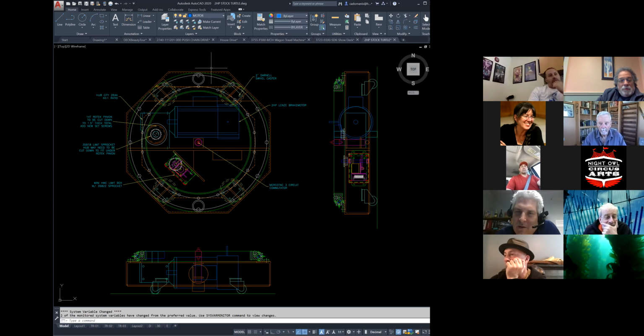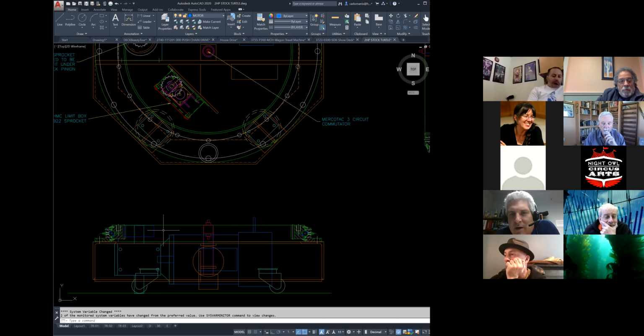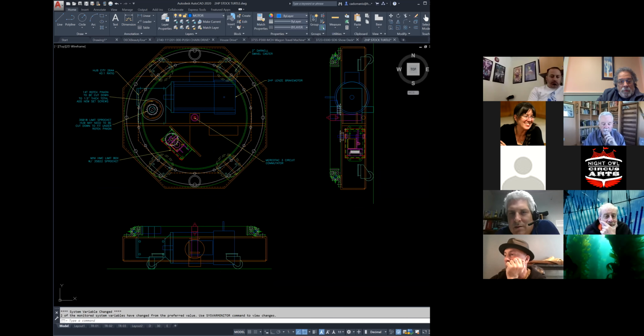In the case of our turtle, we have essentially a little tiny wagon. This is about 3 feet across on the 2 stop sign sides. That is what ultimately gets connected to the deck track and runs across in the track. It has a gear motor with a pinion gear bolted into it, and it can then turn this larger geared bearing, sometimes called a slew ring.